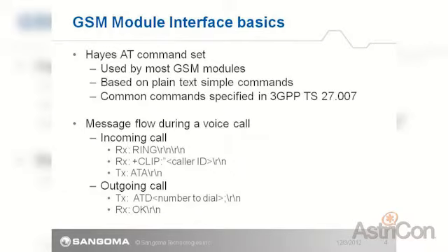It was originally used by modems, but when people started making modules for cell phones, they just reused that same interface. Most of those commands are specified in a spec called 3GPP TS 27.007.